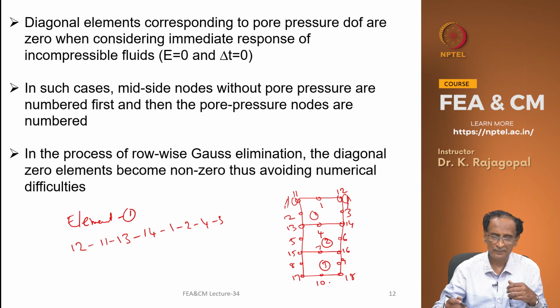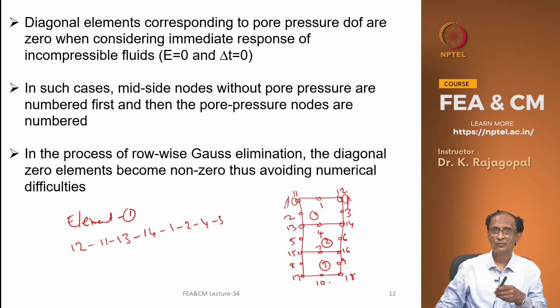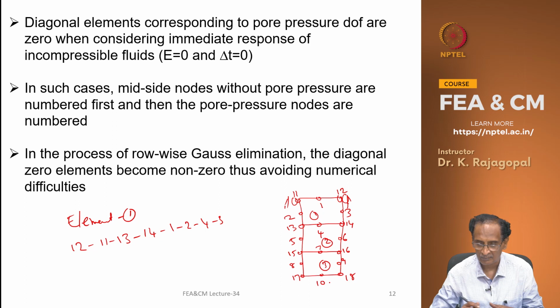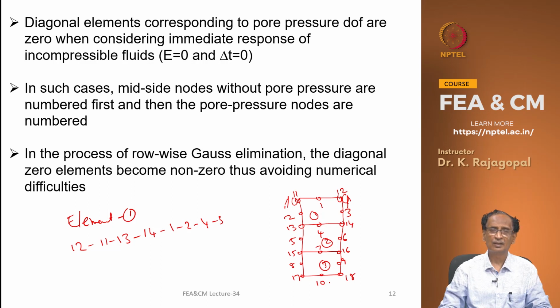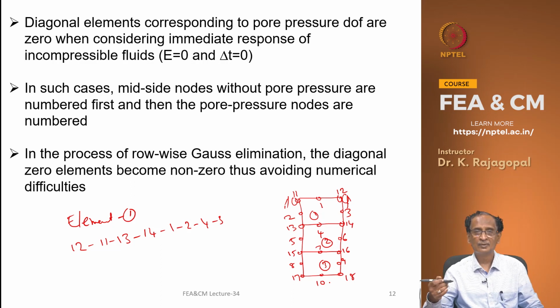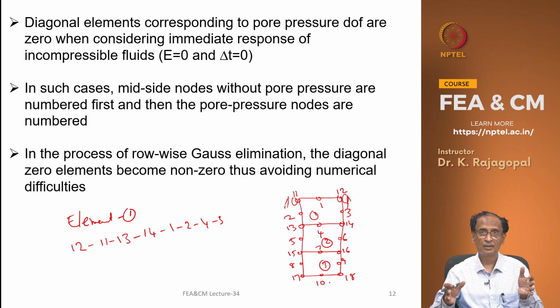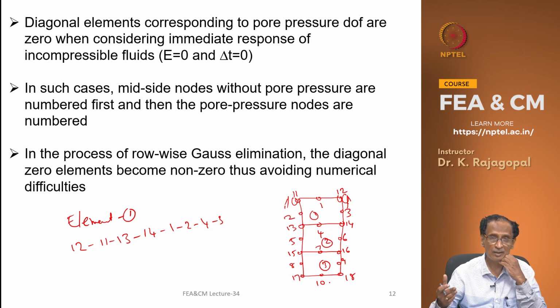And this is one trick that is normally played out for getting the immediate solution. So, this consolidation analysis is usually done with 8 node quadrilaterals, and by using Biot's theory, we get the direct solution of both the displacements and the pore pressures at any time. And if we work with advanced constitutive models like the soft clay model or the modified Cam clay model,